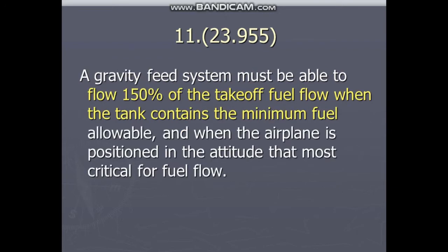Number 11. A gravity feed system must be able to flow 150% of the takeoff fuel flow when the tank contains the minimum fuel allowable and when the airplane is positioned in the attitude that is most critical for fuel flow.